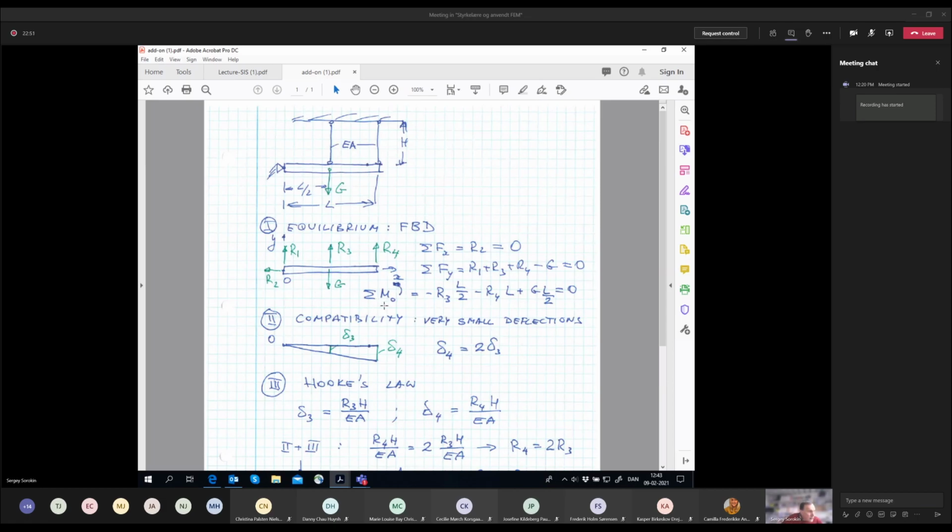So then, of course, I did it in the wrong way here. It's all opposite. I was a little bit in a rush. Please just mark it. So here it's with minus. So of course the force R3 gives the positive moment. The force R4 gives the positive moment, and this force G gives the negative moment. But never mind, while you'll be doing your exercises, I will change this slide and change the signs. But if you multiply it with -1, it will be okay.